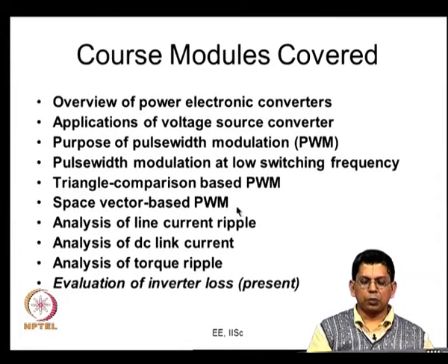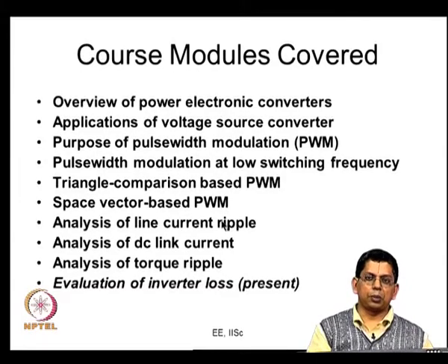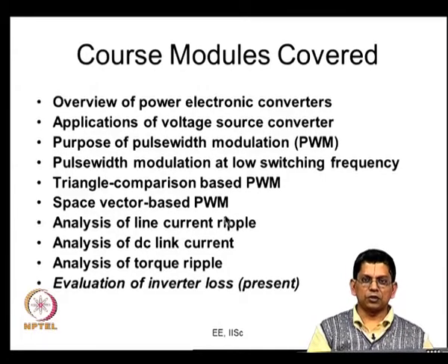Whereas in space vector PWM you can have that division of null vector time between two 0 states, and you also have the freedom to apply an active state more than once. So, there is also a division of active vector time. This additional degree of freedom in space vector based PWM leads to what we call advanced bus clamping PWM methods. These result in bus clamping just as the discontinuous PWM methods do. A phase would not switch in some region of the fundamental, it would switch at the nominal frequency in certain other regions, and at double the nominal switching frequency in some other regions.